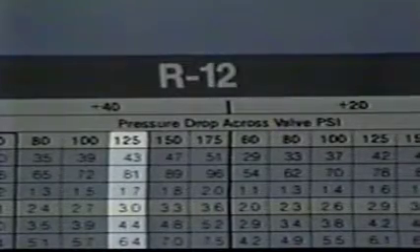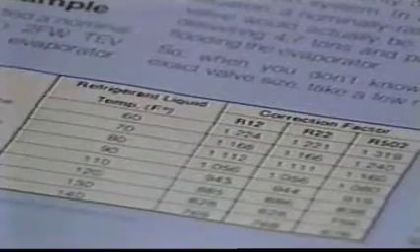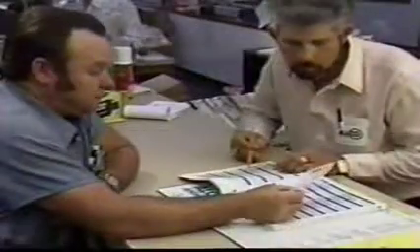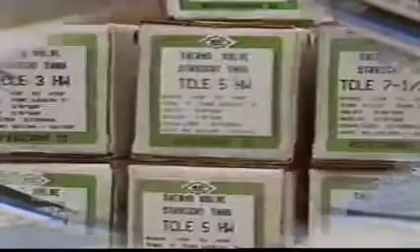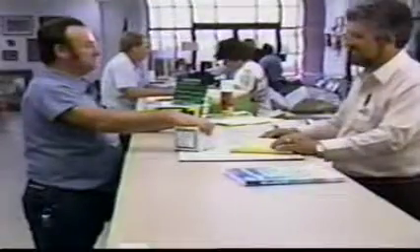Where liquid line temperature is different from the rating temperature of 100 degrees, the user may need to modify his selection after adjusting for the difference. Selecting a valve with all factors taken into account will provide maximum capacity at a minimum cost. And that's enough to keep any customer.